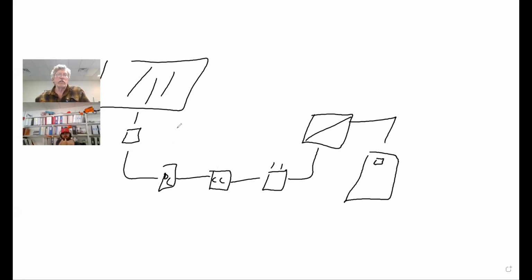So the charge controller controls the array's charge to the battery bank. And these things need to be compatible. But often it may also go out, say, to a load dump. And typically that's going to be a hot water heater. So what it's going to do is it's going to say, okay, I'm generating power. The sun is out over here. Looks like a fried egg. And I don't have enough load to service. I'm generating more power than my loads require.